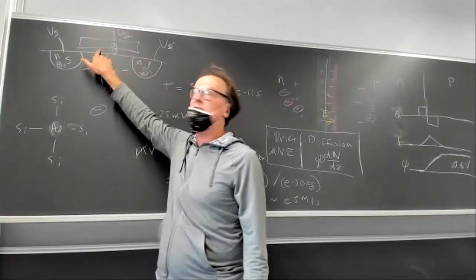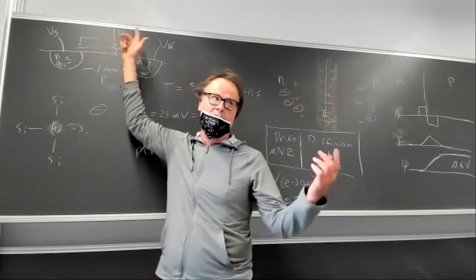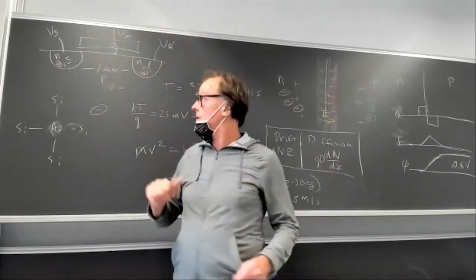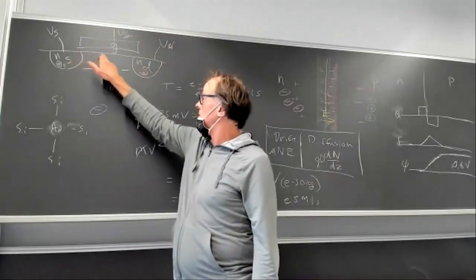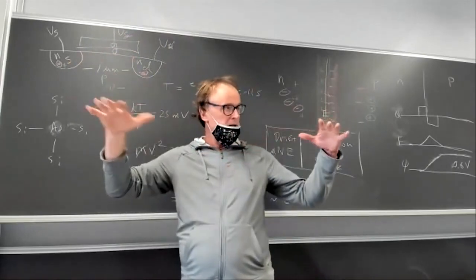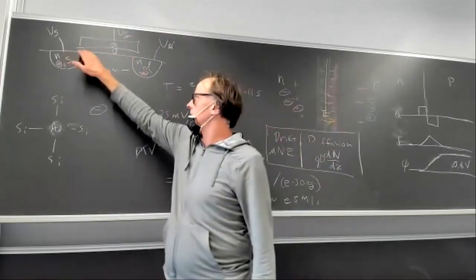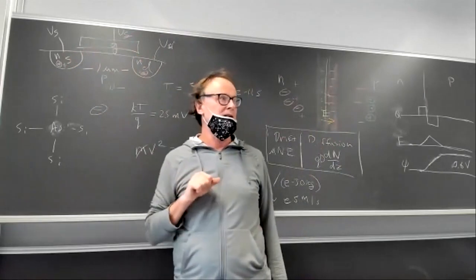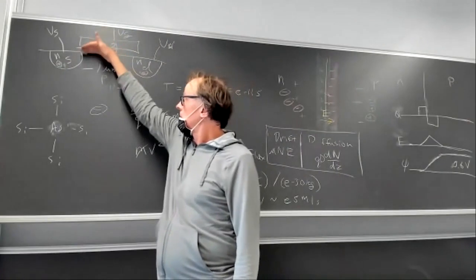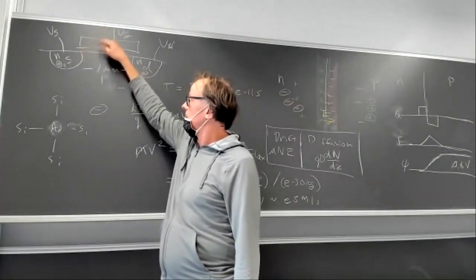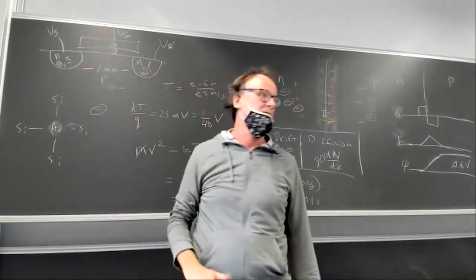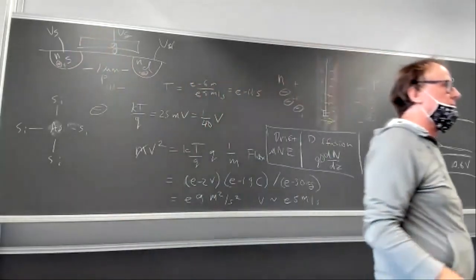This is an insulator here, right? That's gate oxide, silicon dioxide. It has a band gap of about 8 electron volts, huge band gap. But right below that, the channel is a two-dimensional, almost two-dimensional plane right at the surface between the source and drain. Basically, it's right at the surface of the silicon, right at the boundary of the silicon dioxide, the insulator.